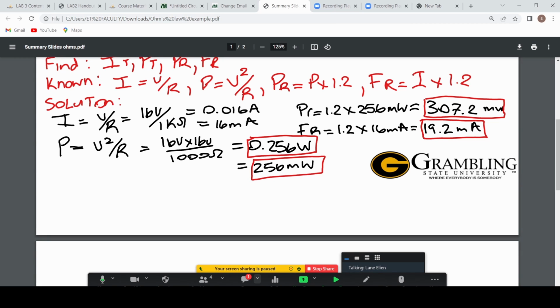Of course, if you go to buy a fuse, you may not get a fuse that is rated this low. Now, when you select a fuse, you think about, okay, what is the application? What is the total current my circuit is going to use? And of course, you also think about, okay, what is the current that's going to damage my components? And most times you take the next fuse up. The same way we take the next resistor up for the resistor power rating, we take the next fuse up.